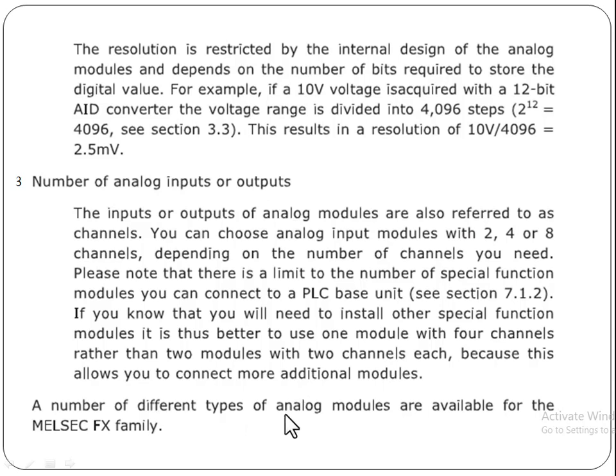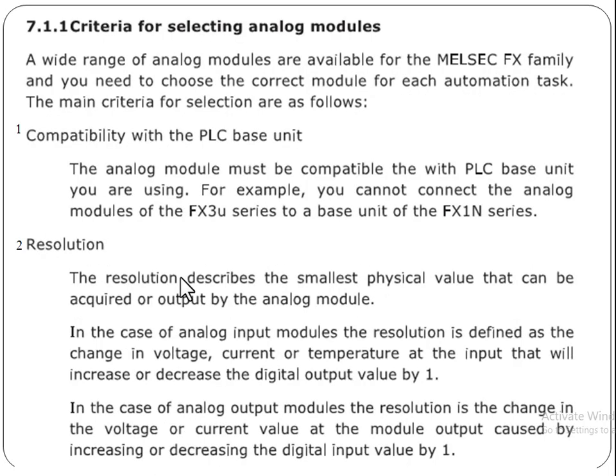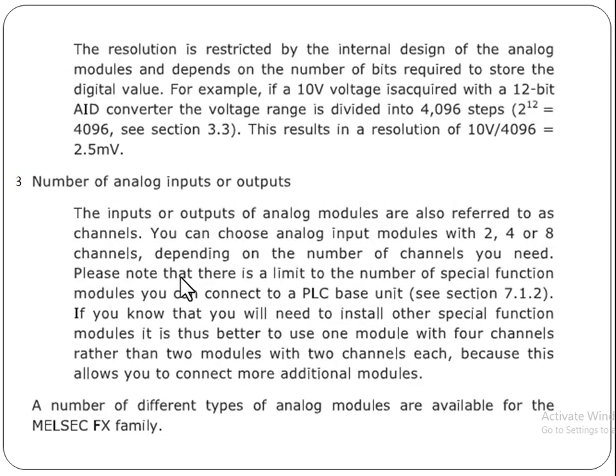Different types of analog modules are available in the MELSEC FX family. So these three factors are very important. First one is compatibility with the PLC base unit. Second one is the resolution, how much resolution you require for the change in the voltage, current or temperature at the input, and current and voltage at the output. And third factor is the number of analog inputs or outputs available on the analog modules.